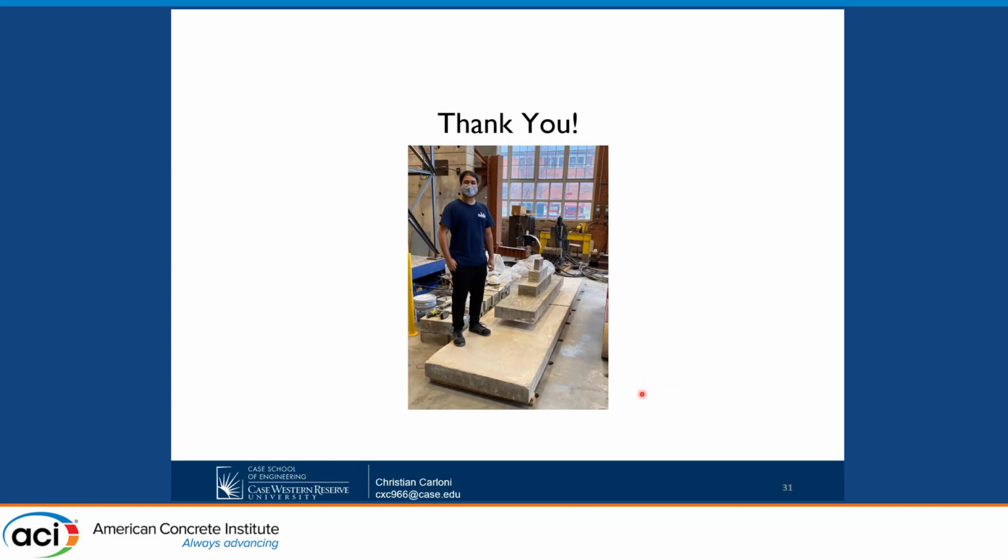So do we have any questions for Christian? Yes, sir. Professor Carloni, actually very good presentation. I have 2 questions, very fast. The first one is, as you mentioned in the technical literature, it's hard to compare the values, right? Because we don't have a lot of information. But is it possible that in the case of UHPC, instead of decreasing the shear capacity as the size increases, we can have some different trend that increases the shear capacity? And the second question is, I know that size effect is related to the aggregate size. However, in UHPC, we don't have large aggregate size. We have only maybe less than 8 millimeter aggregate size. Do you think there might be any fiber interlocking action that can generate this or compensate this effect?